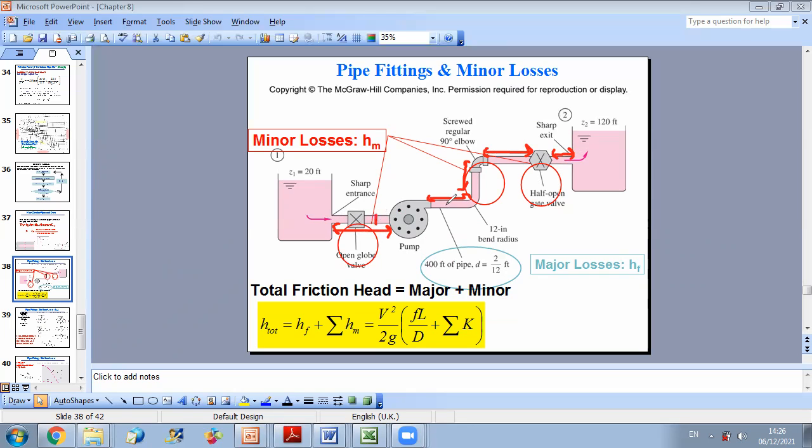Since we have the same diameter, this means that we'll have the same average velocity at any cross section because of continuity. From the continuity equation, if the cross section is not changing, then V average times A times rho equals m dot. For steady applications, m dot in equals m dot out, so the mass flow rate should be uniform everywhere.